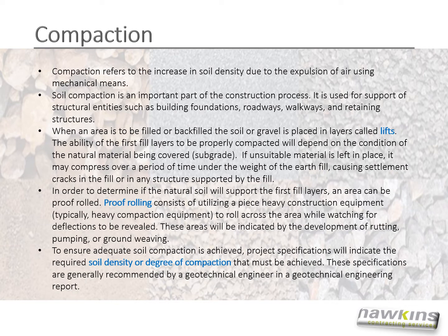When an area is to be filled or backfilled, the soil or gravel is placed in layers called lifts. The ability of the first fill layers to be properly compacted will depend on the condition of the natural material being covered. If unsuitable material is left in place, it may compress over a period of time under the weight of the earth fill, causing settlement cracks in the fill or in any structure supported by the fill.